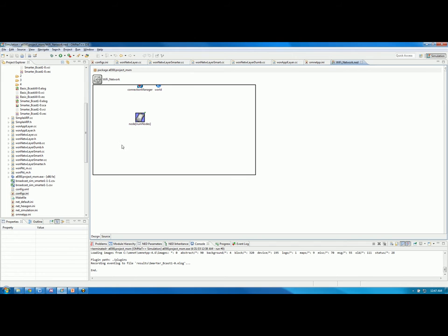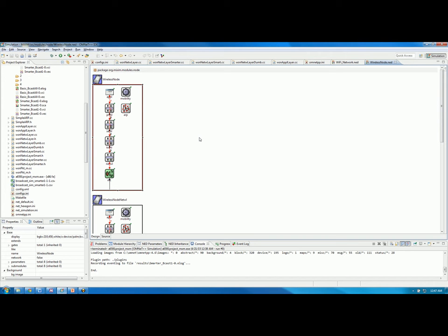So the first thing to do was develop my model for a wireless sensor node. To do that, I used essentially a toolbox like MATLAB called Mixim. It had various blocks that I could throw in here for the different OSI layers. I chose to implement their physical and MAC layer interface, the network interface card essentially, and I'm going to develop a custom network protocol and bypass the other layers and just start broadcast and manage everything at the application layer.